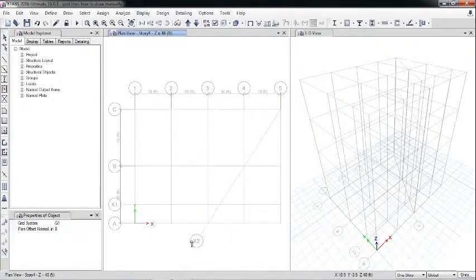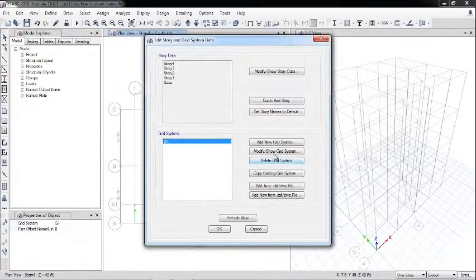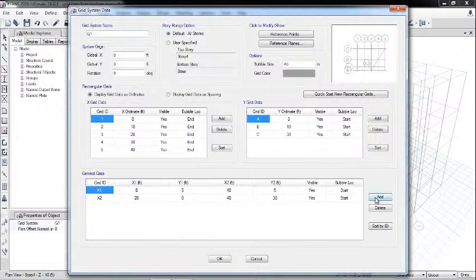So now there is a third option. You can also draw by manually putting the coordinates. For example, I will add new grid x3 and I will put x1 y1, x2 y2, meaning 2 points, so it will automatically draw the grid between 2 points.